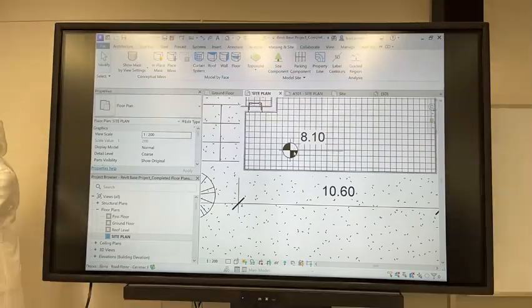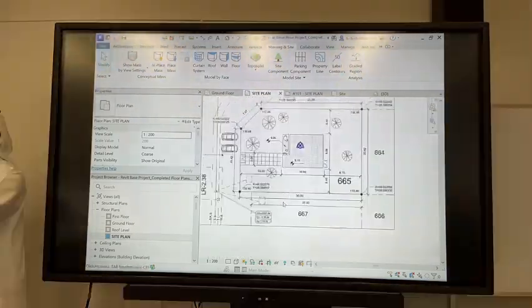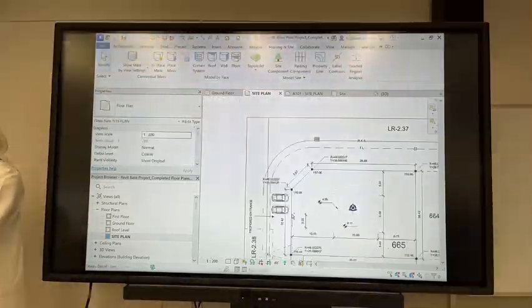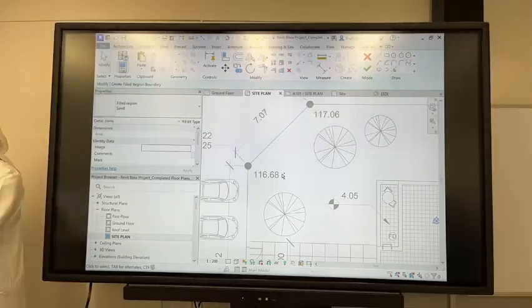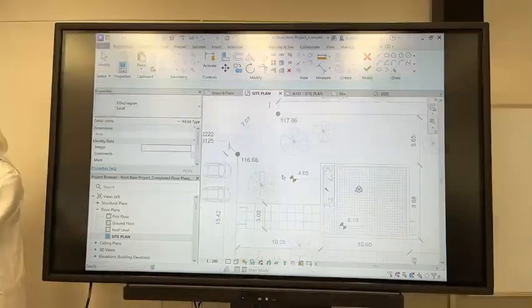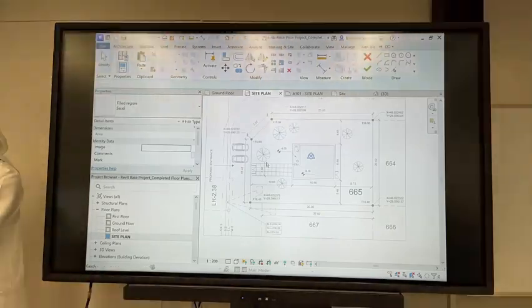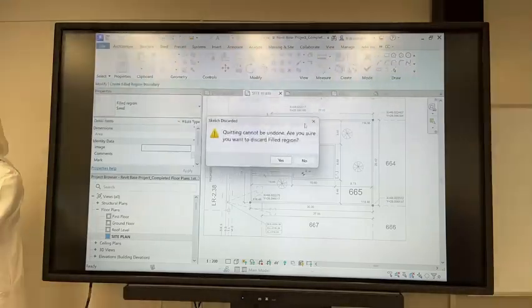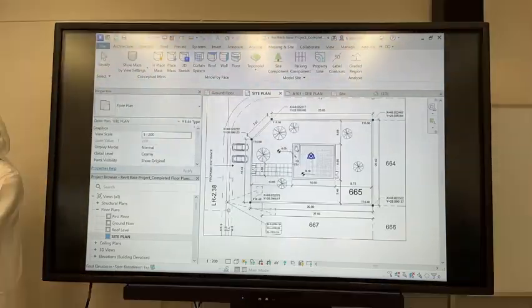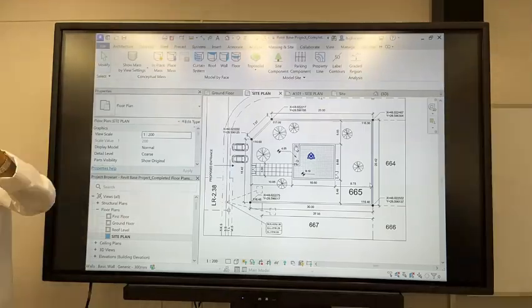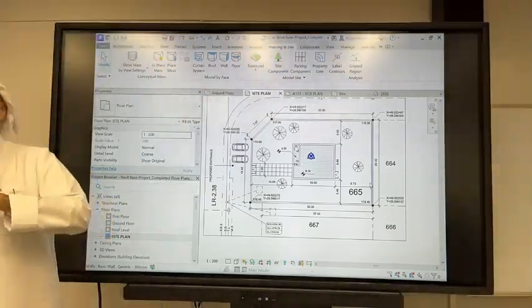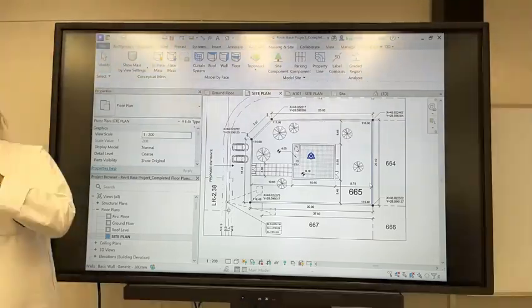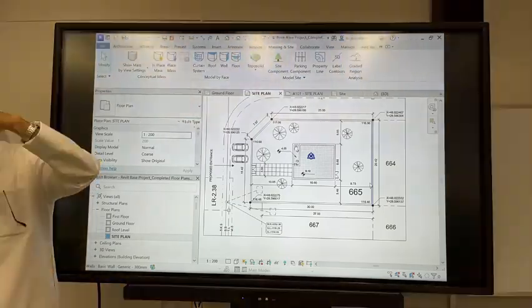One last thing. Look here, actually two things. The fence. How do we draw a fence? The fence now runs on the property line. How do I draw it? Wall, exactly. What are the settings of the wall? First thing, its base is what level? Which is what? Ground is not 0. Ground floor is plus.